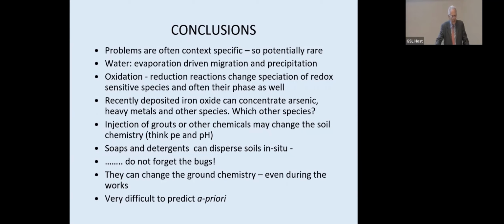The laterite, I first met it where it was the detergent precursor, and it had caused localized collapse and also erosion. It seemed to disperse the soil, so the soil was eroded. And the lab had taken some of the soil, some kaolin, mixed it with the detergent material, then filtered it on a filter paper, and it had all passed through the filter paper. It was that finely dispersed.